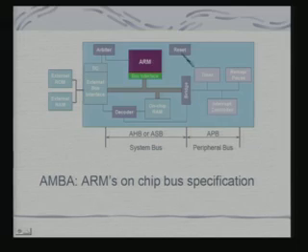So, you go back to the picture that we had already seen earlier. So, you have got this ARM processor, it has got its bus interface, making the interface compatible with what is called AMBA bus. Now, obviously, when I am having a bus and definition of the signals, they may not be always same as that of the signals being provided by the processor core.